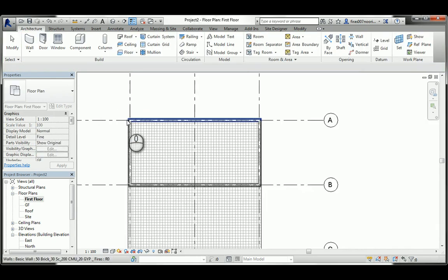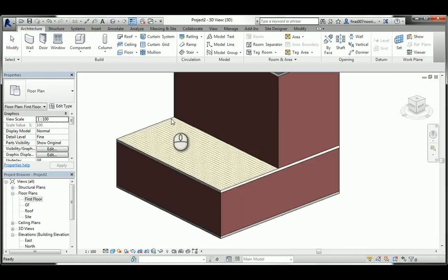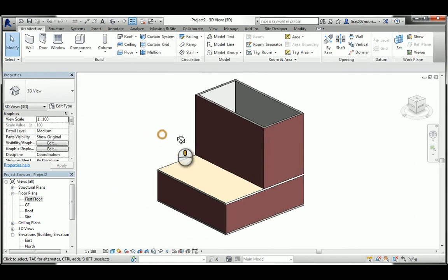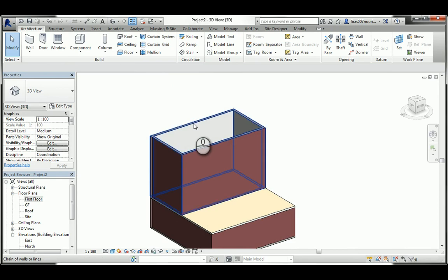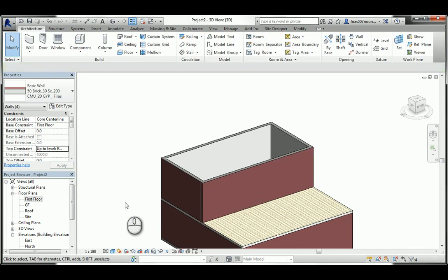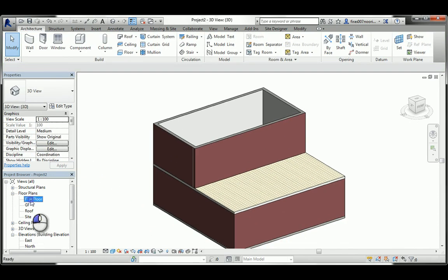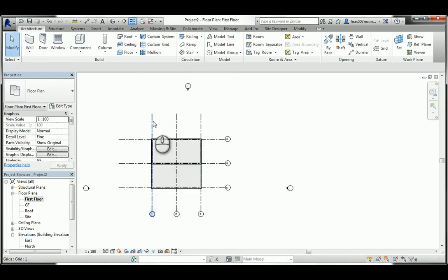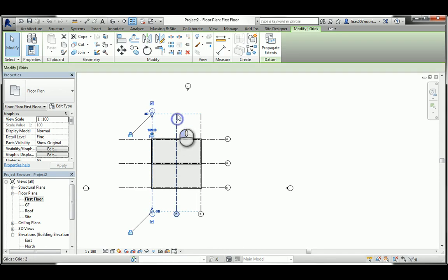See, now go to 3D. Ugly long walls, I know. Just click them with the hover and chain thing, and then go to roof and hit apply to fix the issue. So in the first floor, you might notice a little bit of some mistakes, which is this is not being shown. It's okay, just click them and show the bubbles here.